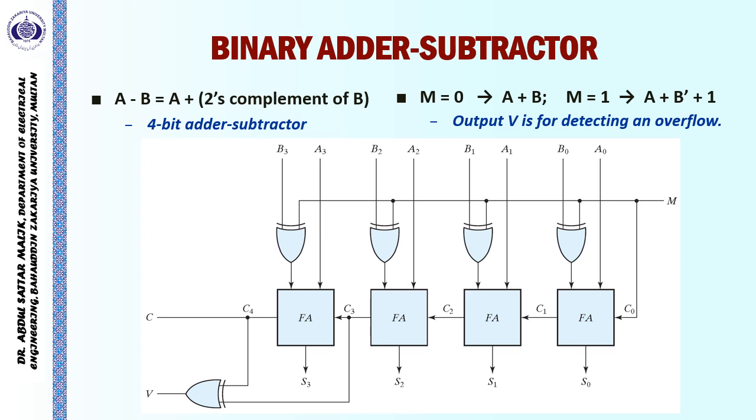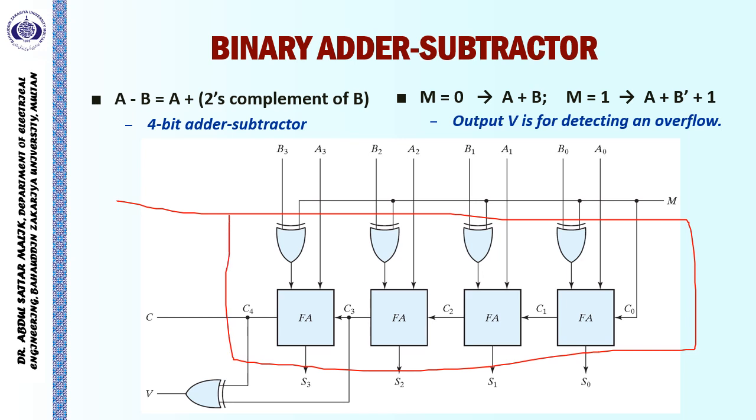So if a number is in 2's complement form, then whether the result of subtraction or even addition of two signed numbers can be stored within the 4-bit information, or the result is going out of range, will be indicated by the overflow bit.